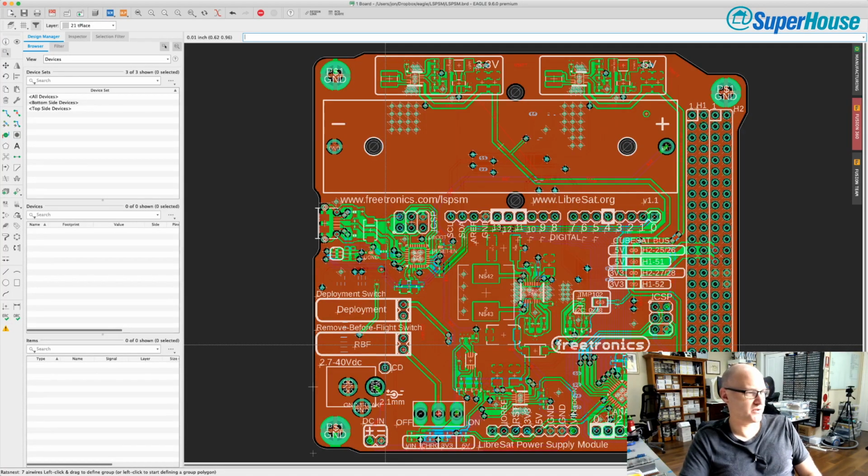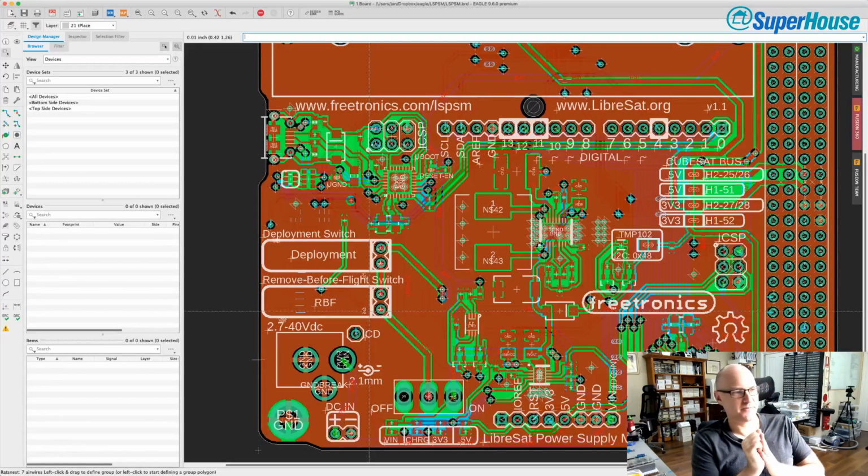And the very last thing you do before it is launched is you pull out the red tag and it removes a safety interlock. So the RBF is satellite, and when it's sitting inside its deployment device, the switch is depressed, and then when it's deployed, the switch is released and it powers up the satellite. The reason for that is that you do not want the satellite to be using any power while its solar panels have not been deployed, and more importantly, while it is within the launch vehicle, or in the case of RGSat, within the International Space Station, because we don't want the transmitters firing up or doing anything like that. So there are these two mechanical interlocks that are used to prevent it powering up.